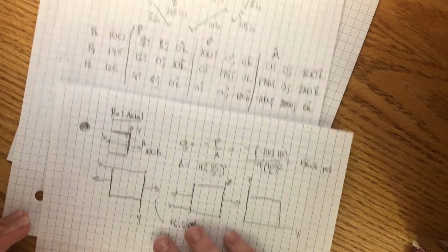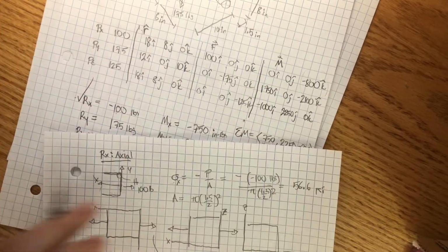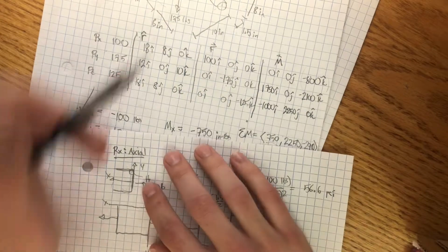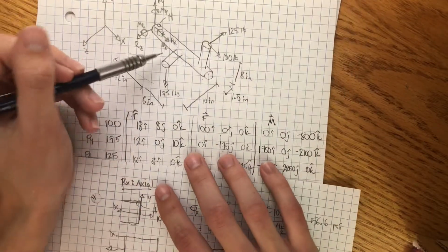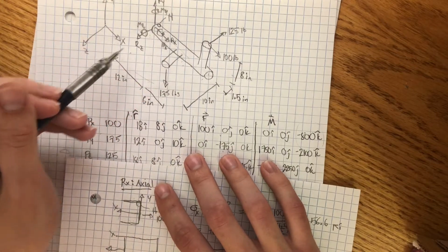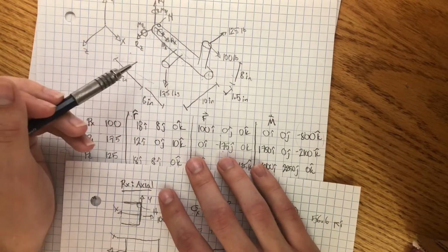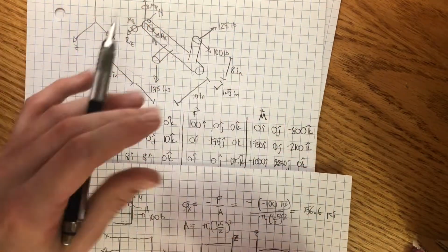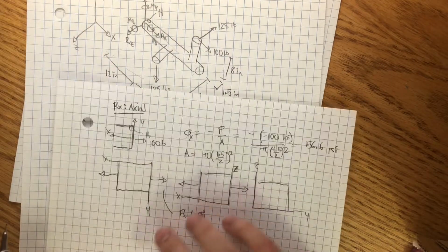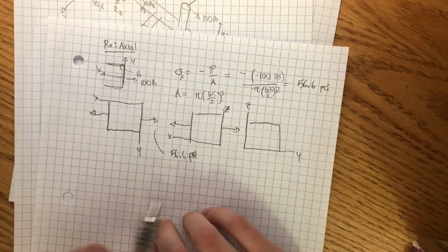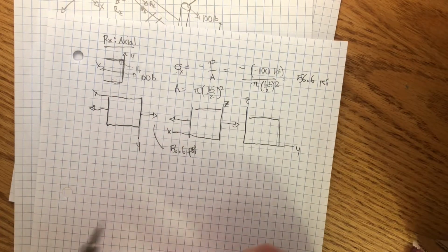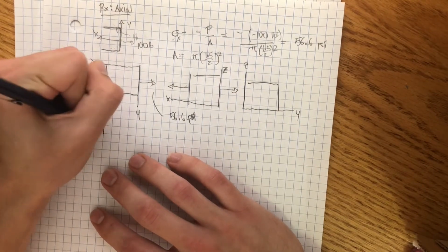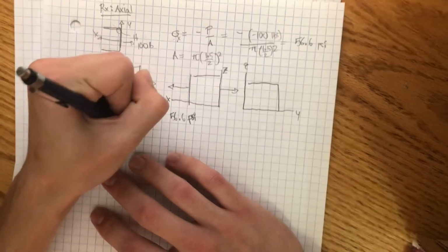So now what we're going to do is we figured out all the stresses and stuff caused by Rx, and we're going to look at Ry. And Ry, as you can see, it's not like Rx. It's not axial. It doesn't follow this tube. It's perpendicular to it. So that's a transverse shear reaction, all right? Because it's creating a shear force. It's not going to be creating tension and compression. So we're not going to be worrying as much about normal stress as much as the transverse shear stress. So for Ry, transverse shear,